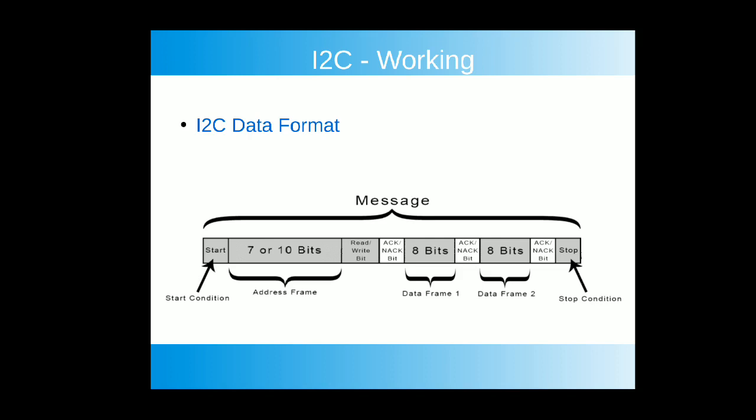And we know that in the idle state, the I2C bus has both SDA and SCL lines at a high voltage level. When the master wants to write to or read from the slave devices, the master will bring the SDA line voltage down to a low value, followed by the SCL line voltage to a low value. And this sequence indicates it is the start of a packet.